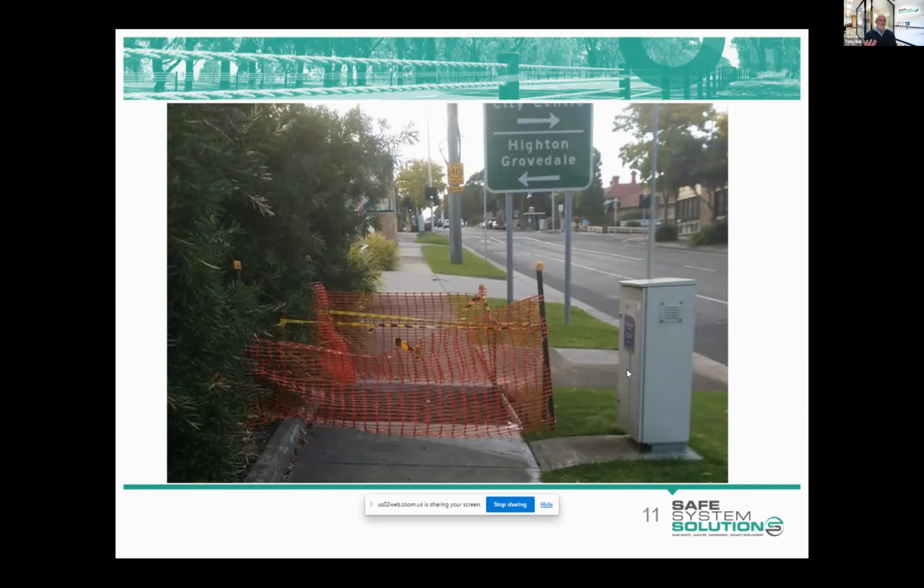You could provide traffic control to help them across the road, and it's probably another half hour on your day to fill that up, compact it, and when the concrete's arriving, take that out and provide a safe crossing point. It's just a bit of pre-planning to ensure that we're not causing any grief to people who are going to be using that footpath. Because if you're on a scooter or some sort of mobility aid, getting around that would have been very difficult.